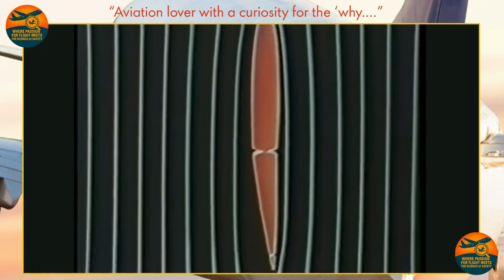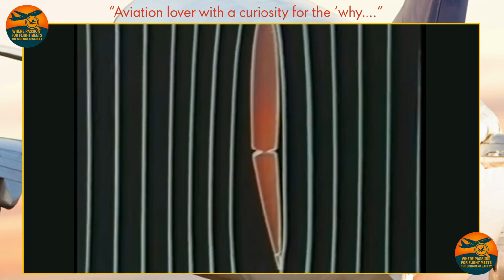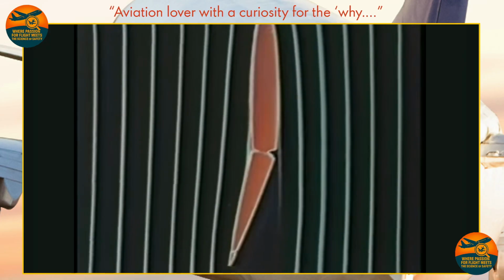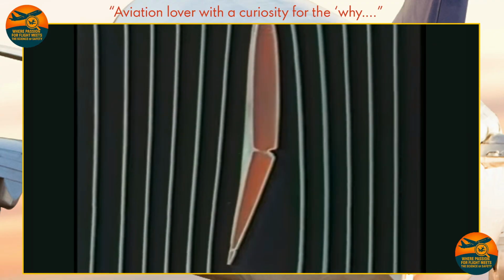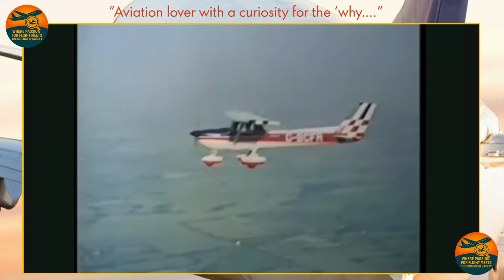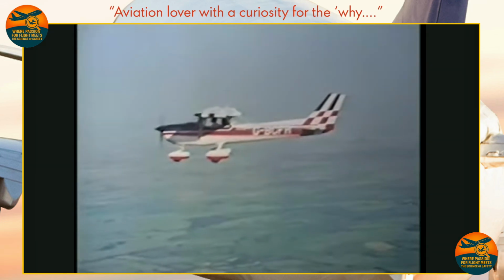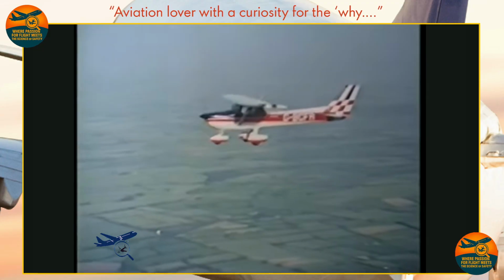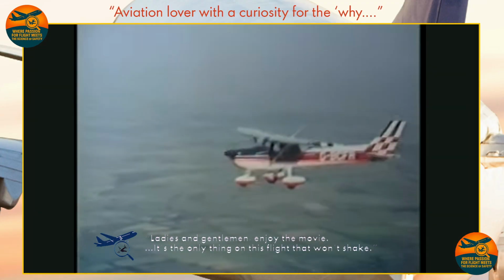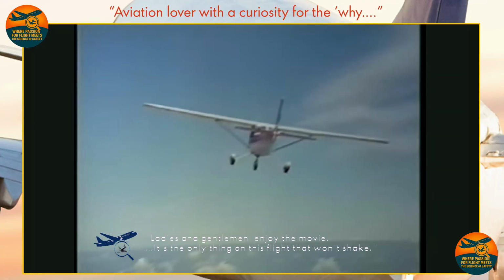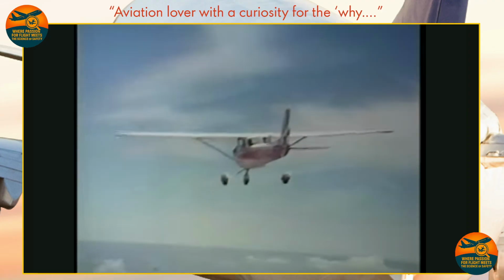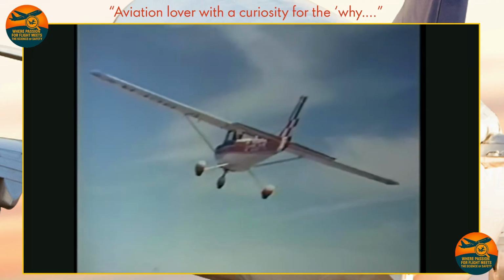The rudder works in just the same way in the vertical plane, with the airflow deflected to the right or left, so as to push the tail in the opposite direction, swinging the aeroplane around its vertical axis. The ailerons deflect the airflow in the same way, but in opposition to one another, depressing one wingtip and raising the other at the same time, controlling the aeroplane around its longitudinal axis.